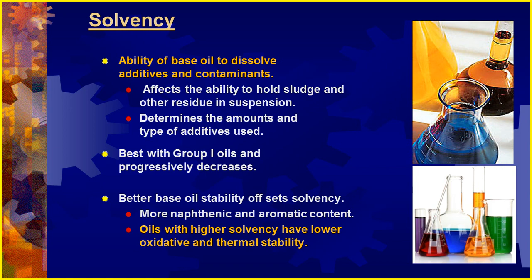Solvency. Now this is a very, very important situation. The solvency of the oil. This is where esters are important with PAOs or your synthetics. Most of your naphthenics or your Group 1s or 2s are able to absorb chemistry very, very easily without needing help. Your higher-end Group 3, 4s, and 5s, especially with your synthetics, they need help with esters for the additives to be able to work together. So the science of it, beyond the base oil, is the compatibility with the additives and everything to work together in a synergistic or complete environment.